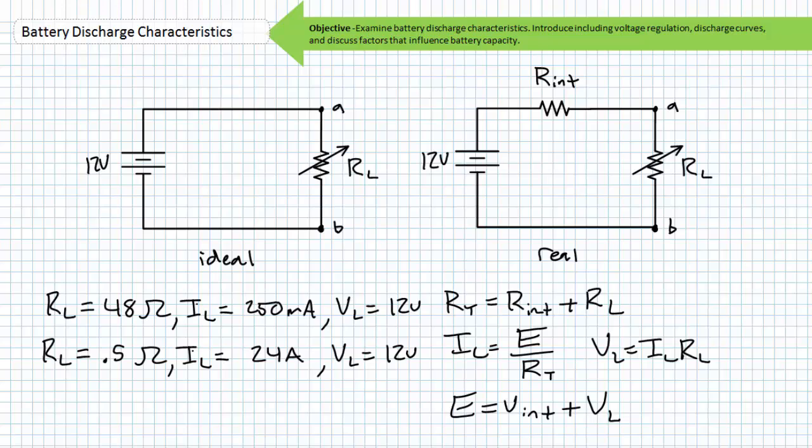Resistance in series adds up. If the resistance increases, current decreases. Being a series circuit, it can be said that current through the internal resistance and the electrical load is the same. Given current travels through the internal resistance, there will be a voltage drop across it.